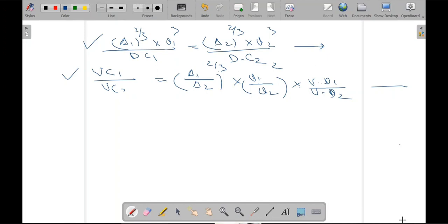What is a voyage consumption? Let us say VC1. When I say I am making a voyage, how much fuel you are consuming in a voyage will depend upon voyage days. Suppose it is a 10 days voyage and I am using 30 tons per day, so my voyage consumption will be 10 into 30, 300 tons. So voyage consumption is voyage days multiplied by DC1, daily consumption.